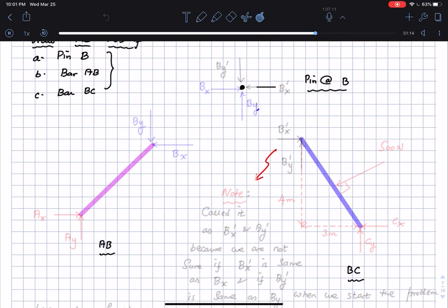Okay, now we're going to be drawing all these forces. I start off by looking at the reaction forces. So I'm going to have a force AX and AY pointing vertically up this way, pointing this way. So this is AX, this is AY. Then I'm going to have a force on the pin at C. This is going to be CX. And I'm just taking them in some arbitrary direction. So these are actually the support reactions, right, at the point C and at the point A.